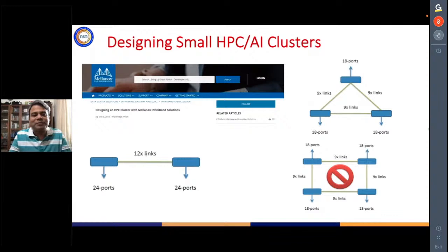Now, obviously, there is a limitation on what size of switch you can make. You would see there are large switches as well. If you are from the Ethernet world, you will see there are switches which contain 1000 ports or 500 ports or 40 ports or 100 ports. Even in InfiniBand, there are switches which contain 1600 ports. But this is not a single ASIC. It is actually a big device which contains multiple ASICs inside, connected to each other in a certain way. For a single ASIC, there is a limit to how big it can be.